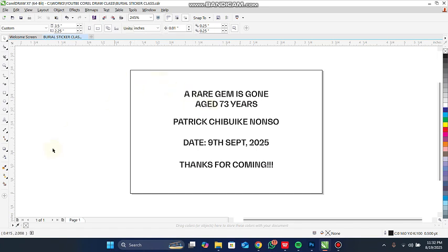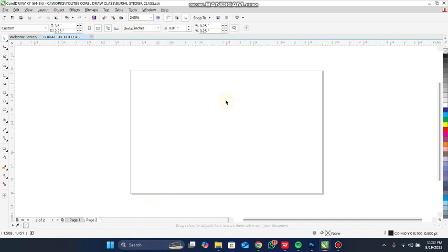Alright. So now I'll just insert another page. This is page 2, where this plus button here is why I can just click here and I'll have my page 2 automatic with the same size layout, because this apply to all pages is turned on. When I allow it on all pages, that means whatever sizes I customize will be applied to all pages. But if I leave it on this current page, whatever size I applied here will only affect a particular page.